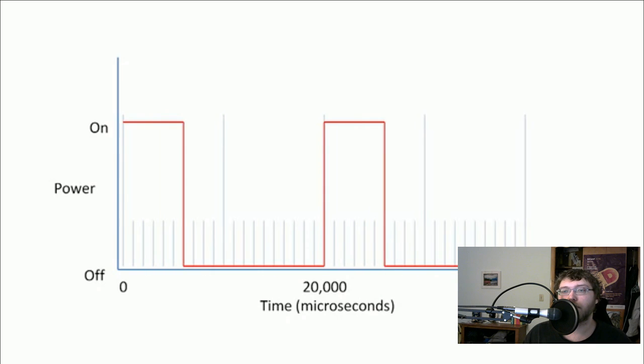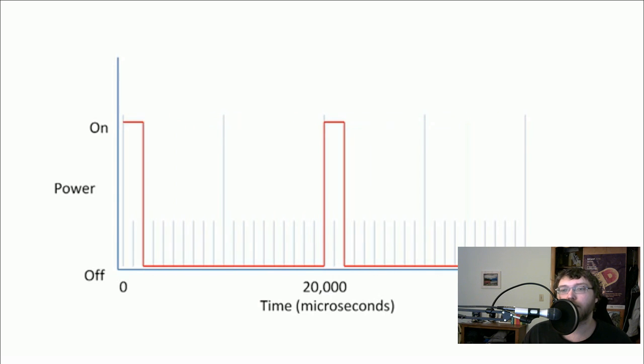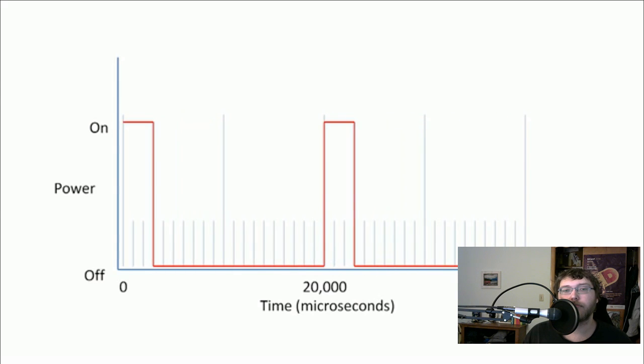This animation shows a PWM simulation. The cycle time is 20,000 microseconds or 50 Hz, and the resolution is 1,000 microseconds, giving us 20 levels of output. For your application, the required resolution and overall cycle may vary. Simple displays require very little precision control, and sometimes a little flickering is not the end of the world. For more advanced displays, the ability to control the levels of brightness might be more critical. For example, the issue of mixing colors using an RGB LED. The trade-off is simple. More control and accuracy requires more and more microcontroller resources.